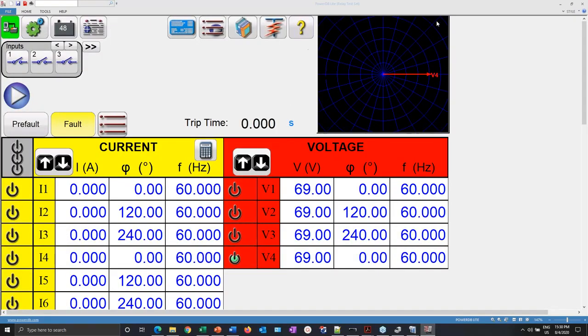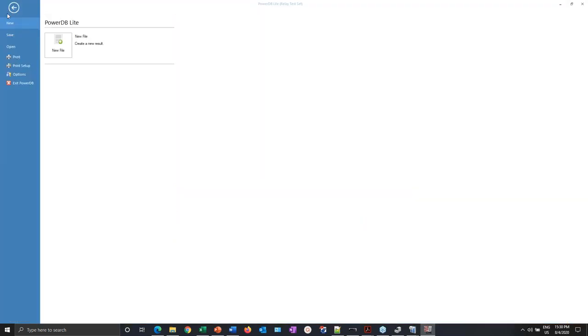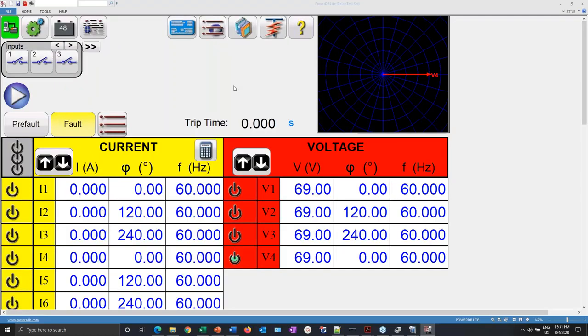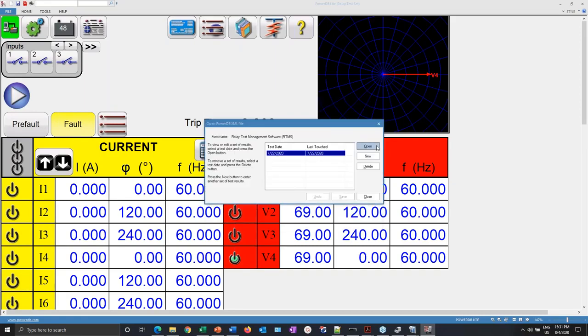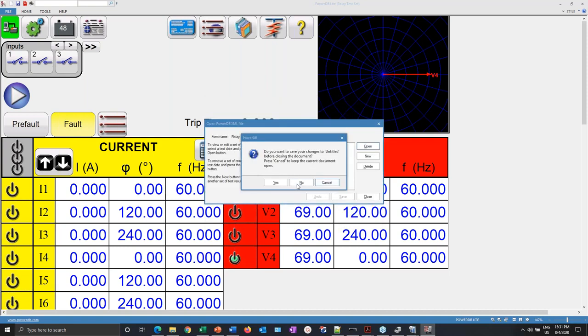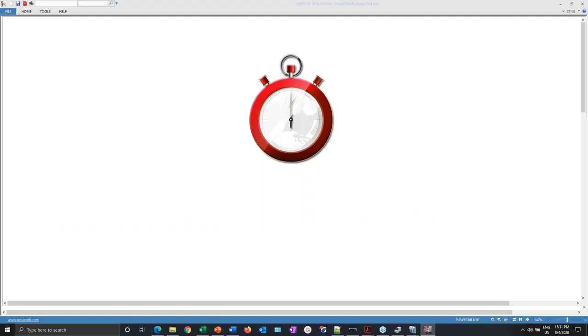Yes, you can. Every time, like Abel was showing you when he was doing the time overcurrent test, whenever he created that test and went into that feature in that module, he would run that test and put in his settings, or read the settings from the relay, as he was showing when he was scripting the settings to mask the buttons and features inside of the timing screen.